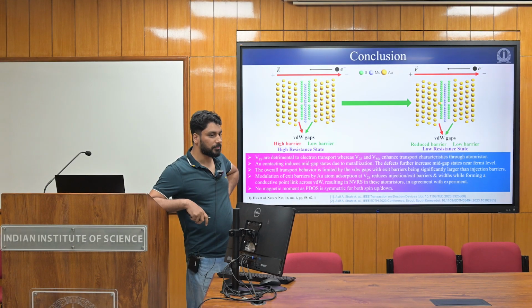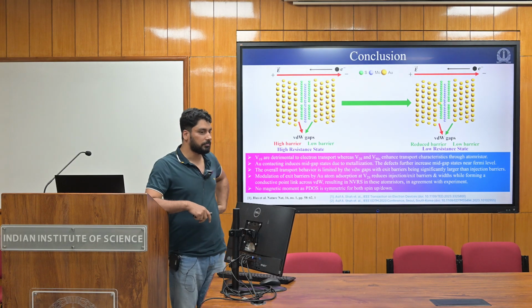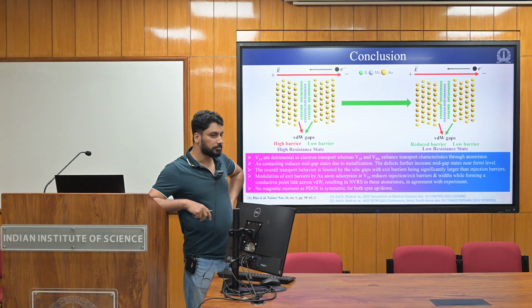You answered earlier. When you come to fabrication, the whole game is in fabrication. Right? Yes. So when you fabricate, that's a difficulty with the Au-MoS2 kind of interface when you create defects, right? With temperature and surface roughness, you may not get exactly the devices you computed while doing the DFT. So how will you take care of those things in the experiment?